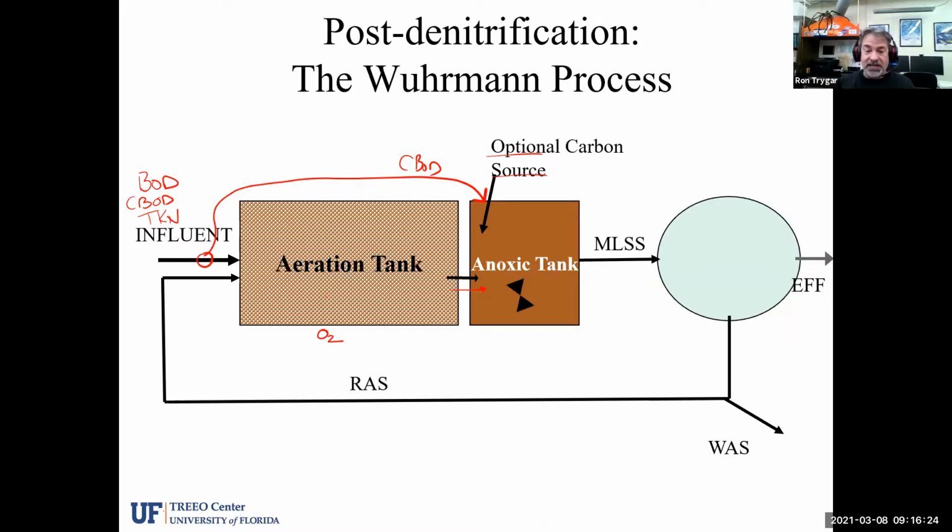The CBOD is not a purified or pure carbon source. It's not easily assimilated. Remember that influent wastewater has chunks, or particulate CBOD, in it, and it also has some that's soluble, but a lot of it is particulate. It would take time for the bacteria to use as the carbon source, so that wouldn't be as available as, say, a purified source. The other thing I want to mention is that there's also some TKN in here.